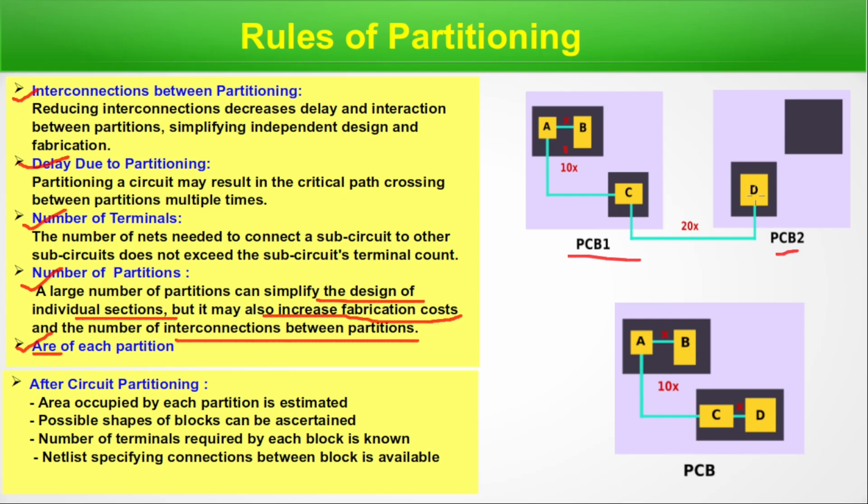Now, if we bring that module into the chip where C is, in another design, then the overall communication time between C and D reduces. So how we place the modules depends on their connectivity, their connections and function, and how frequently they need to communicate with each other. We have to keep it all in mind. That way partitioning can be done. It's not that we do it randomly. Obviously not. It depends on the functioning and on interconnections, because longer interconnection means a lot of time is required. So we have to take care of all of these things.